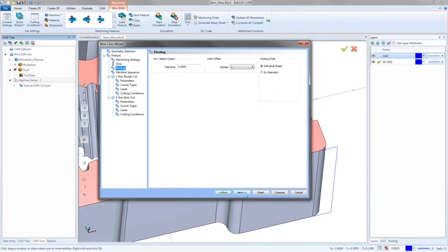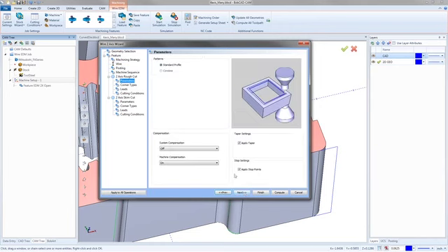The thing with most of these tool paths, especially like the lathe, the wire, the ones that don't have, like the milling has so many different tool paths with so many different settings. With a lot of these, it's a lot of very repetitious kind of things that we're doing. So we got to go in here. We choose our standard profile, turn our machine compensation on. You'll see we don't even get a choice this time. It's a G40, whether it's a G41 or a G42, because it knows to do the machine compensation based on the direction that we're cutting in.